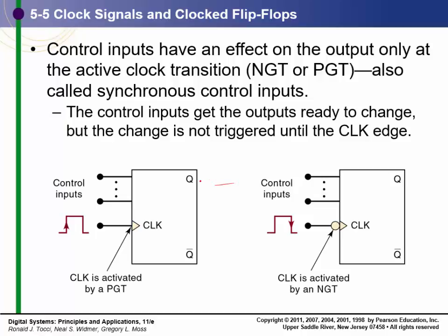Of course, we assume that these outputs are feeding other flip-flops down the road. So we have more than one flip-flop in our system. This signal goes out, and that feeds other flip-flops in our system, and we'll see these circuits. It has time to settle down before the next clock edge, because remember, it takes time from this clock edge before this output becomes stable.